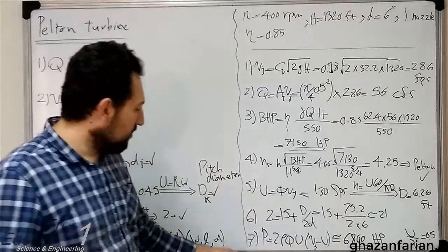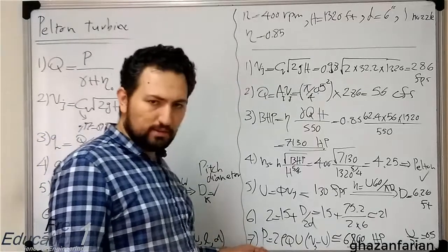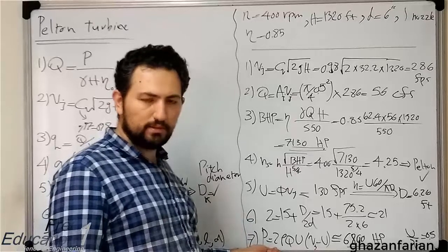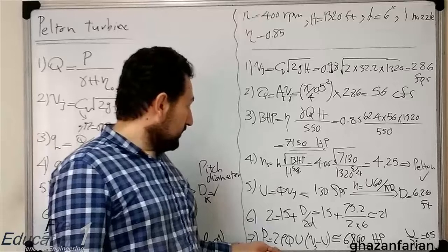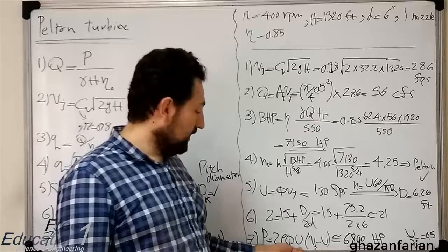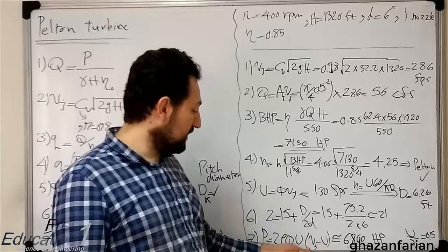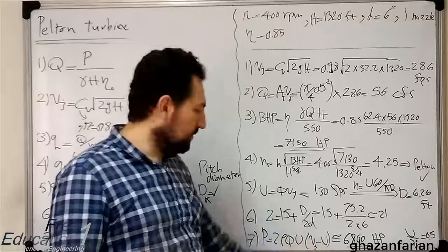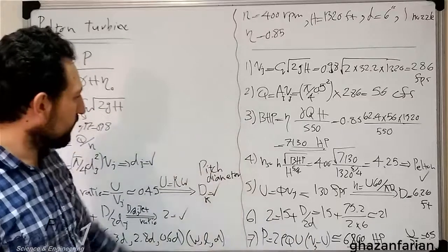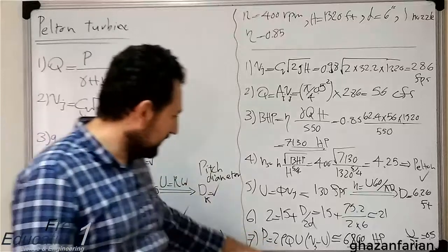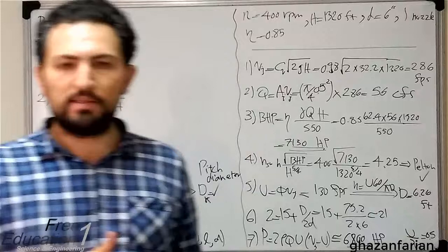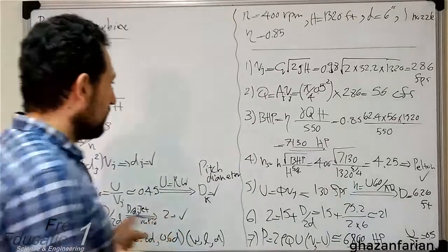In that video I obtained this relation that the power, or the braking horsepower, is equal to twice the product of the density, the capacity, the circumferential velocity, and the jet velocity minus the circumferential velocity. You can substitute the information of this problem in this relation, and also convert the units from standard English engineering units to horsepower.